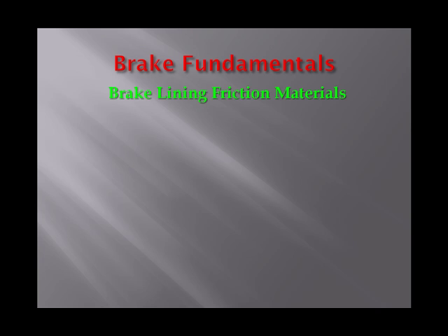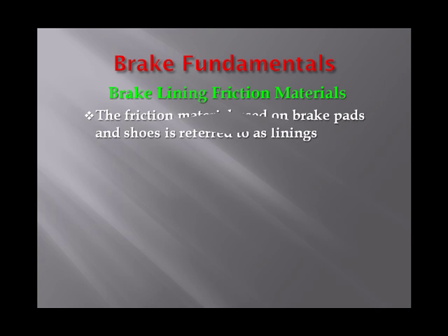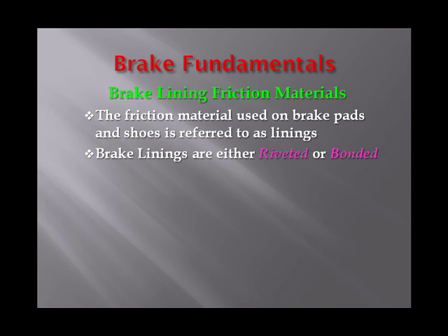Brake lining friction materials. The friction materials used on brake pads and shoes are referred to as linings. Brake linings will either be riveted or bonded to the backing of the shoes or pads. Some newer types of pads are integrally molded. These are easily identified by looking at the back of the pad. If there are holes that are partially or totally filled with lining material, then you have integrated pads.